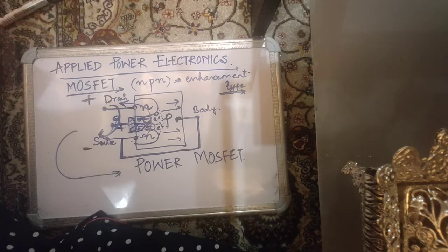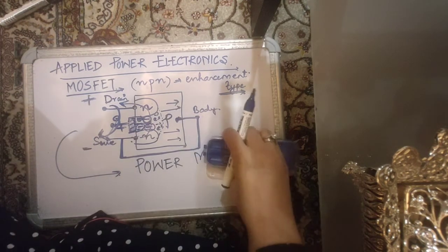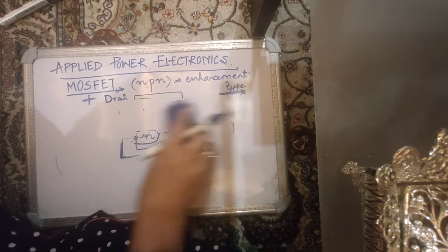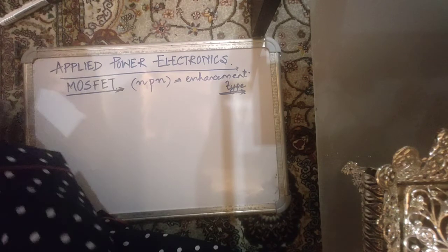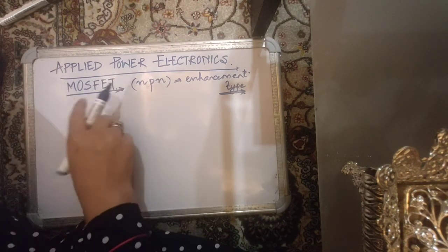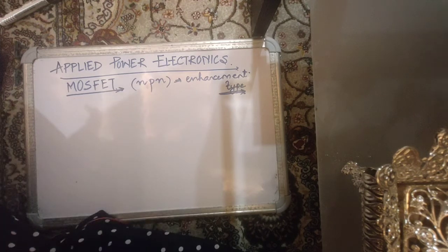When we were discussing the power diode, I also told you that the constructional difference between power level devices and signal level devices is that they have very thick wafer dies, which allows high current carrying capability, and often power MOSFETs are vertically mounted in order to enhance their current carrying capability.